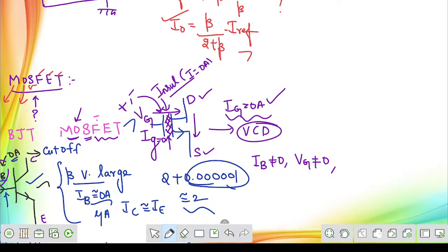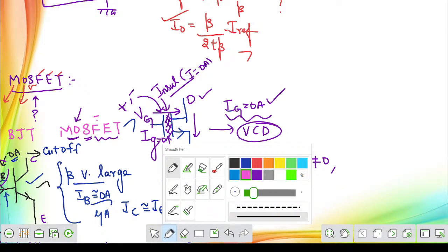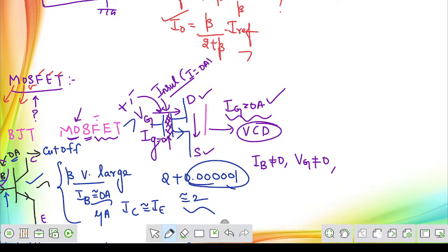See, MOSFET is a bidirectional device. So current can go from drain to source or source to drain, because it is possible for us to make the current flow in both ways. In an NPN transistor, if you are taking a specific transistor, it is not possible. Suppose I am having an NPN transistor, it is not possible for you to reverse the direction. Only one direction of current will be allowed here. But here, the same device can be operated.